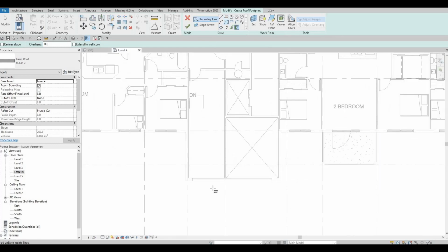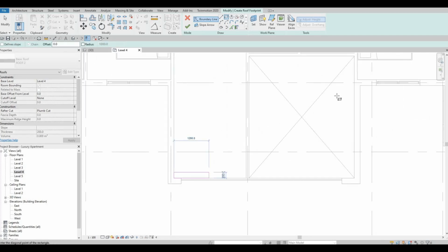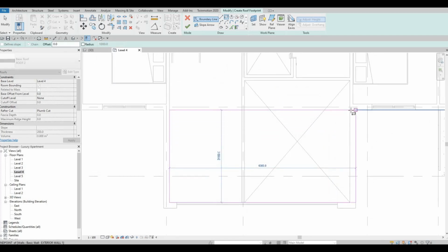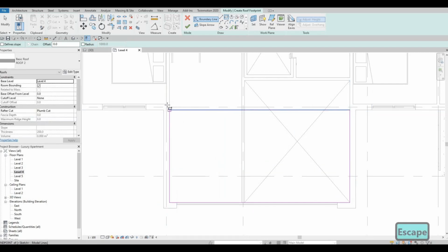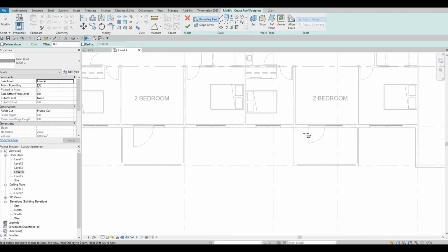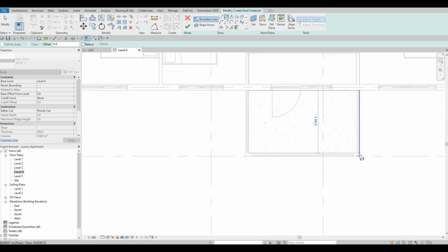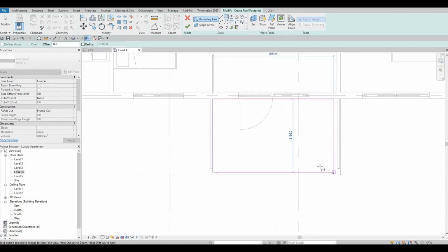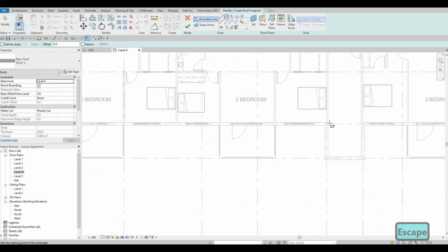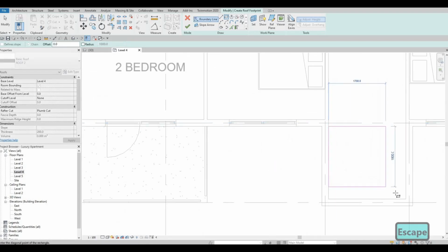And then let's add this one right about there. So don't cross over this because we're planning to add in another exterior wall right here, but with an offset at the top. This one as well, we need to add a wall right here. Sorry, not here, but this one. And then click on finish.